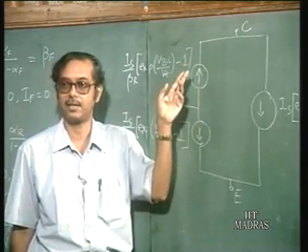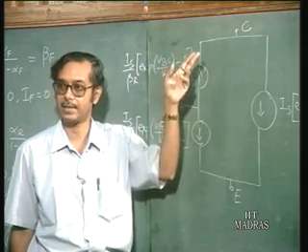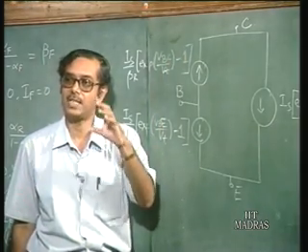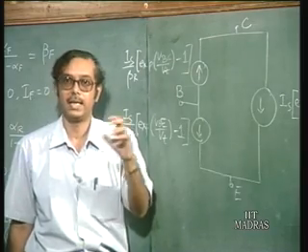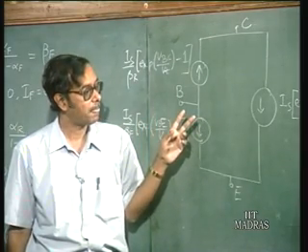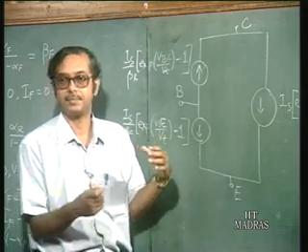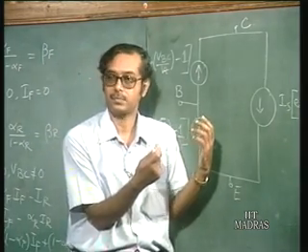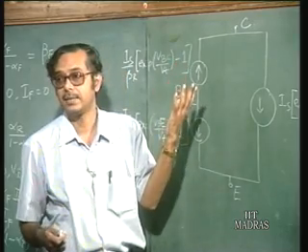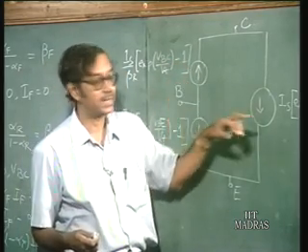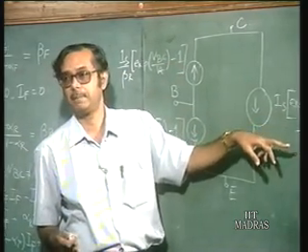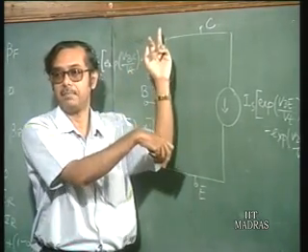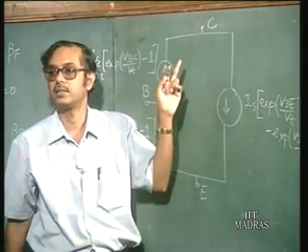There is a negative collector current flowing when VCE is equal to 0. In order to make the collector current 0, VCE should be slightly positive, that is VBE must be slightly greater than VBC, to compensate for this current. These two current sources must be the same so that the collector current is 0.